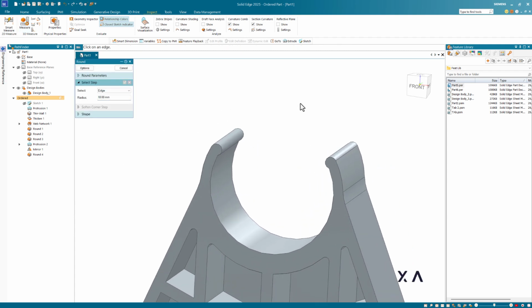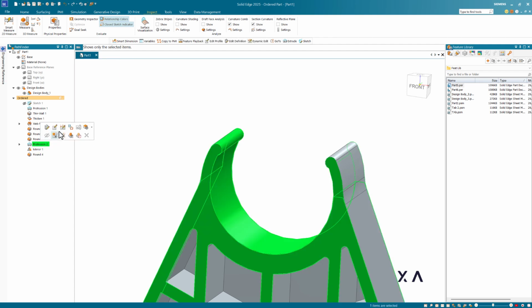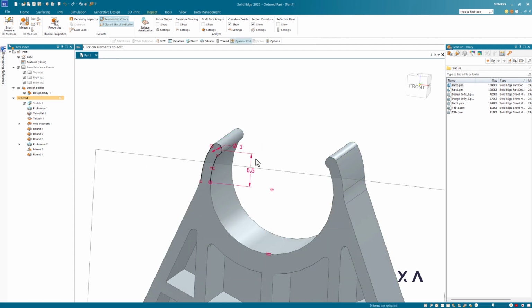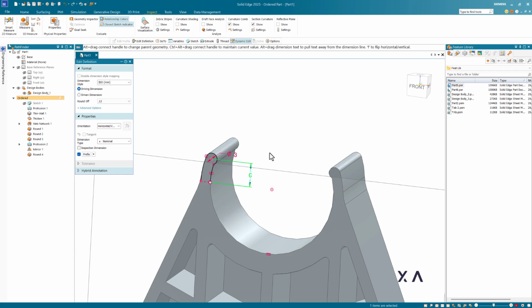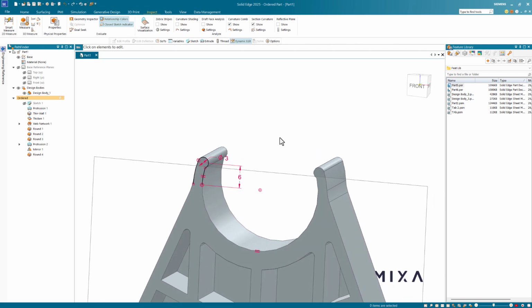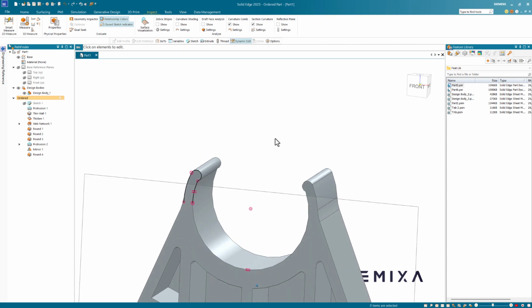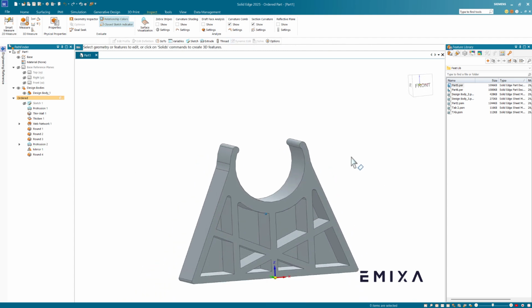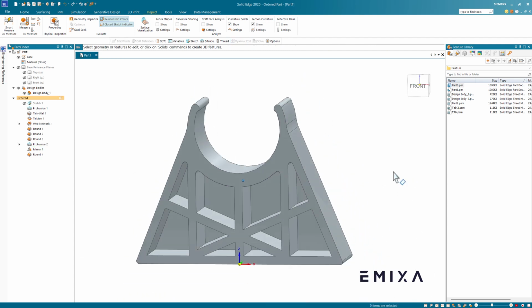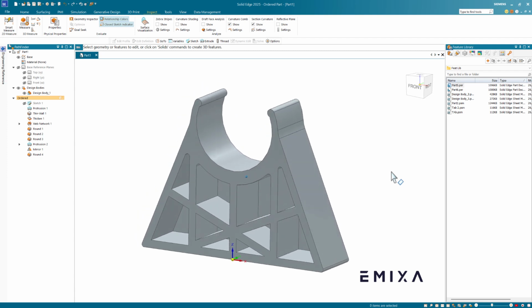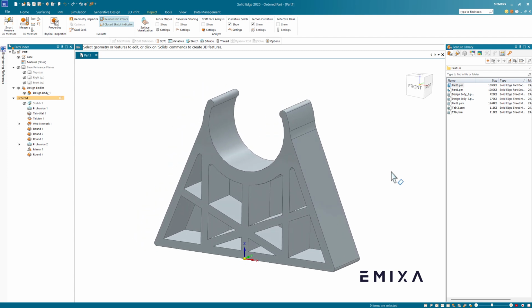If we need to make a change, we can just change that size on this protrusion. We can dynamic edit that and say, okay, let's change that to 6, and that's going to give us a different grip value on there. So we can test that and see how we want that. I've set that to 7.5 now. Okay, so we're ready to save that out now.